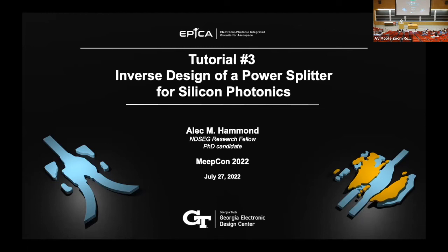Under the hood, we have a function that takes care of this for us, where we actually track the convergence of the DFT fields. We measure all of the regions where we're measuring DFT fields within the simulation domain, and we track how they're changing as a function of time. And once they stop changing by some threshold, which we decide, then we know we've run it for long enough. That's actually the steady state response at that point. We can use that now for our adjoint calculation.